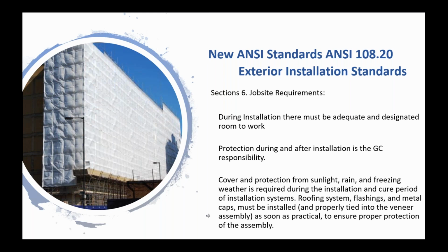They're all good with you getting the tile up there, but the main thing is once you get the tile installed, you have to be careful of the weather, the rain, etc. Once you get the tile installed and the grout installed, then all of a sudden the top is open and they don't put the flashing up on the parapet, water's running directly into your wall. You're going to have some very, very colorful grout. You're going to have probably some latex leaching out of the setting material. It's a big issue.